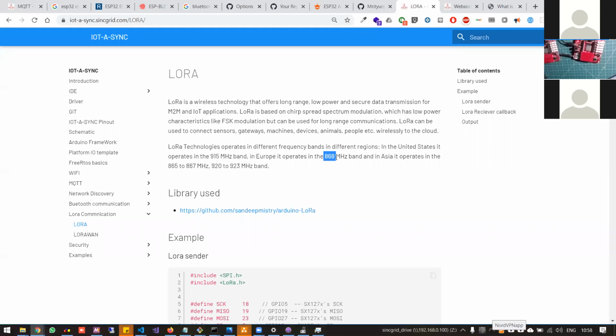For example, certain bands, if you take for example 890 megahertz or some higher bands of 1100 megahertz, 1200 megahertz, these bands are restricted. These are for the 2G spectrum over there. The government allocates or provides them to various operators for a certain time period. But the 865 to 867 megahertz band is freely available for industrial as well as personal use. And in this LoRa module, we are using that.